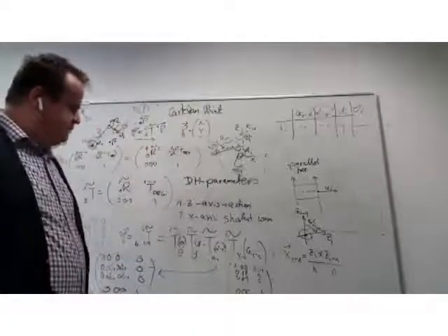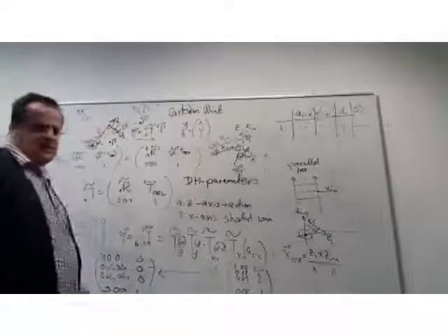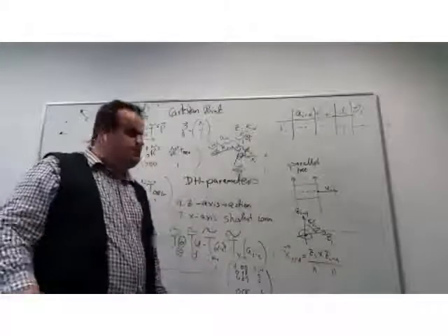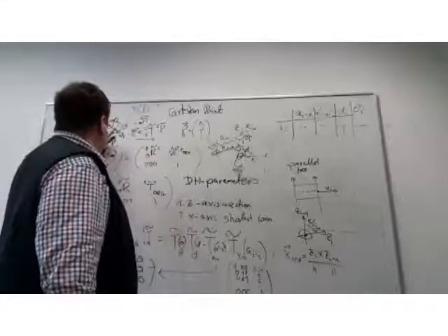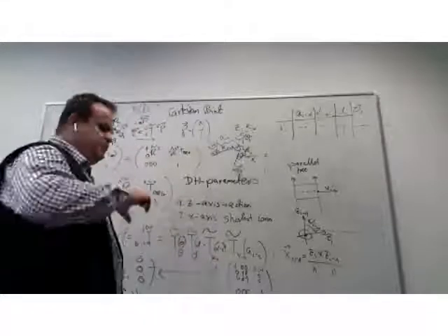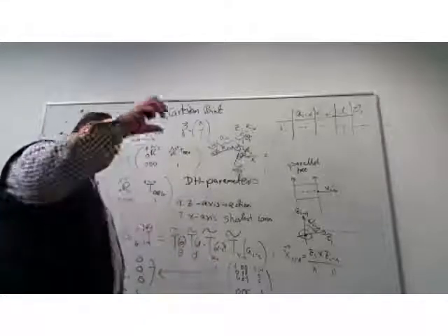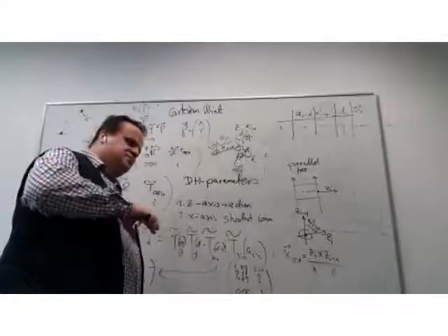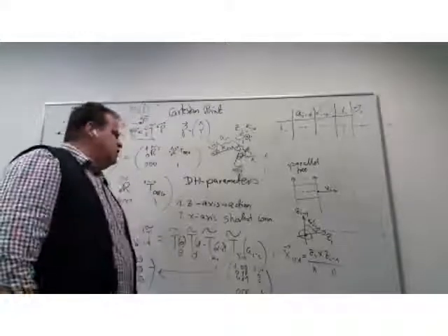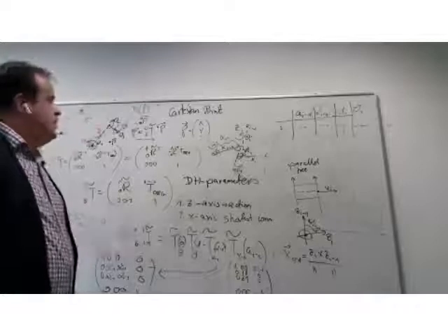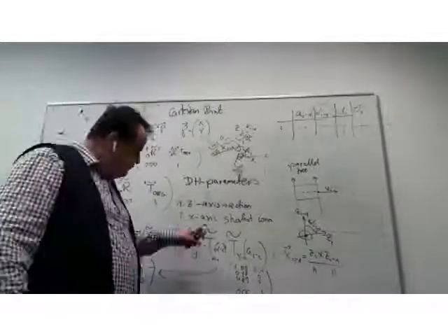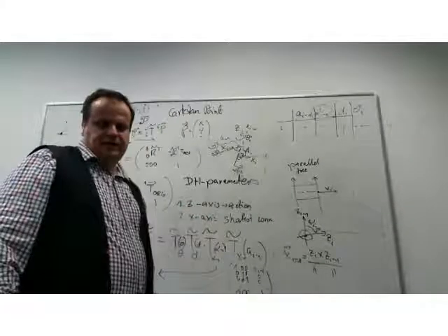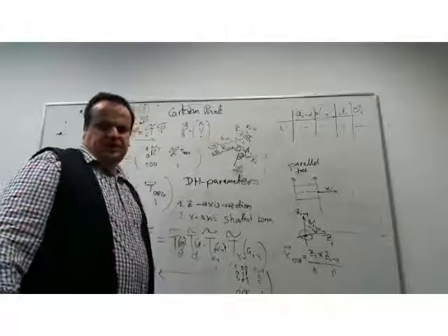And in the end, using Denavit-Hartenberg, we reduced the number of parameters defining the change between the previous frame and the next frame from 6 to 4, but this requires us to actually follow the rules defined by this. And you will see the application of this in the tutorial.